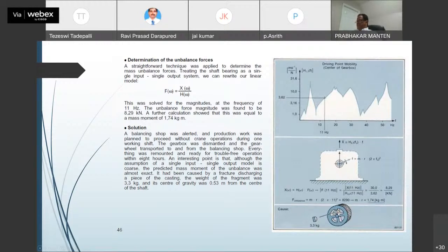So the small eccentric braking and all that. Again, this is to distinguish between, like we said, those steps involved in it: is it an overall structural resonance, or is it a large force caused by this unbalance causing it? So you have to break it up and take a good look at that.